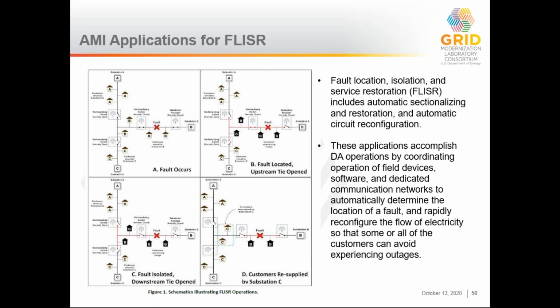Basically, if you look at the distribution system with these sets of houses fed from a couple of different substations, imagine there's a fault in between a couple of different houses, but they're currently all fed from one end versus the other. If they can use the AMI and other sensing technologies to determine where that fault is, automated switching and self-healing systems can help you open the tie downstream, close the other tie, and backfeed to the houses. Then probably the only people actually impacted are the ones absolutely closest to it, rather than what you might be used to seeing when a whole distribution feeder is out for a number of hours because they're trying to restore the feeder from the substation as it was, rather than reorganizing around the different switching patterns they have.